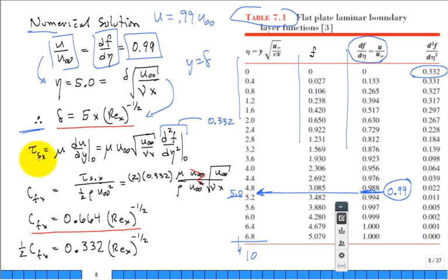So you say, well, what was the law of viscosity evaluated at the wall that gives us a shear stress? Okay, using our similarity solution that devolves down into I need to get the second derivative of f with respect to eta at the wall. I come over here, I say at 0, here's the value of f, here's the value of the first derivative of f, and there is the second derivative of f at the wall. So I put in right here 0.332. And I do some algebra, and I introduce C sub f, which is a normalized tau, and do some cancellation, and here's another big equation that's in every fluid mechanics book.